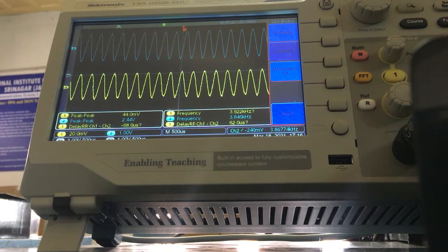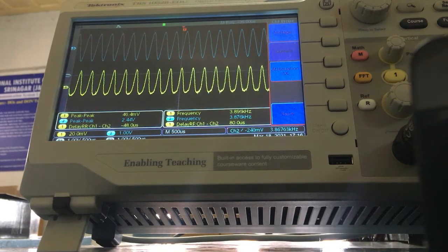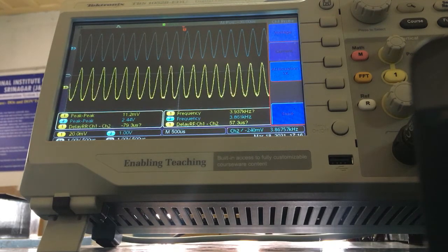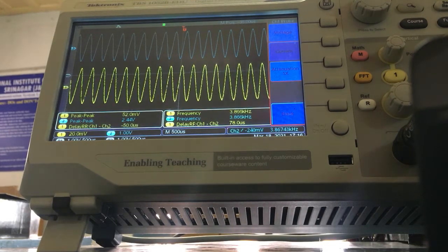But as I increase the transmitter gain, after a certain threshold, the received signal reduces, because there is no automatic gain control in this case, which I've turned off. And if I increase the gain further, your received signal would be diminished to such an extent it would be distorted. But if you turn on the AGC circuit, automatic gain control, it actually looks at the input signal levels, and accordingly reduces the gain as required, right? So for AGC, it's a boon in that case.